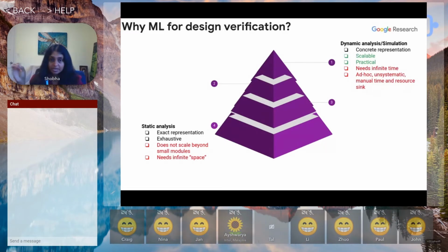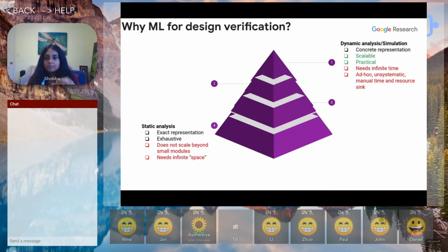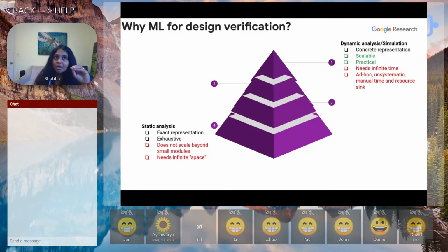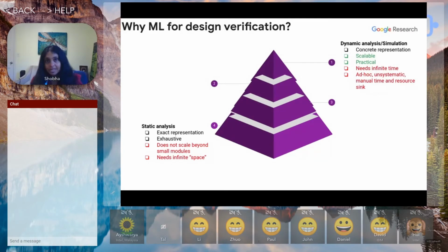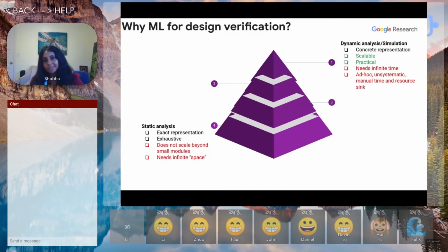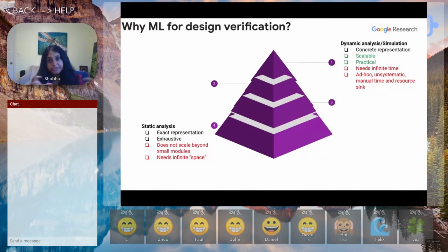If you look at these two types of verification techniques, the static analysis approaches are basically what you would traditionally call formal verification. While formal verification typically is done at the state transition graph level for gates, static analysis is more of a programming language kind of terminology, which refers to analyzing the model of a system. That model can be a program, it can be RTL source code, it can be a higher level abstraction graph than, say, a state transition graph, but whatever.